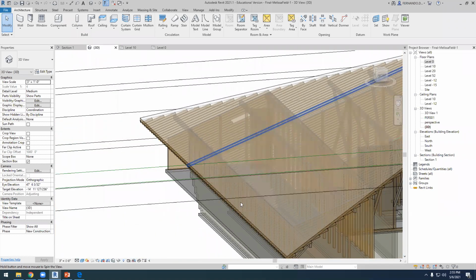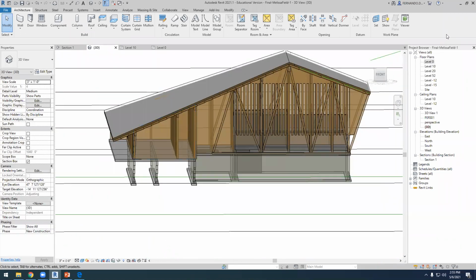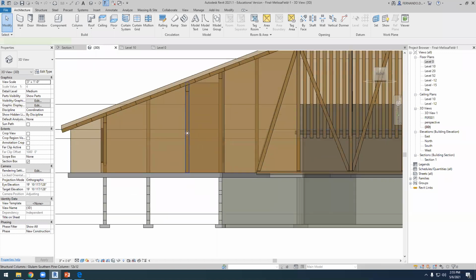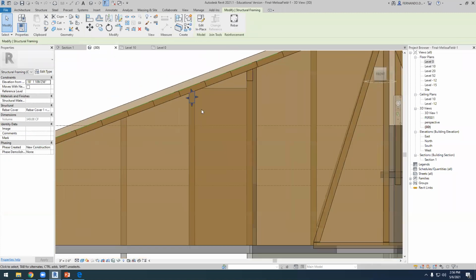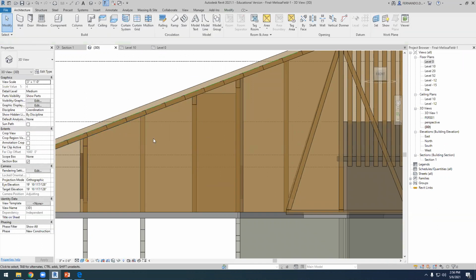So here we have structural elements, we have vertical and horizontal elements. We know that we have these two rows of this one and that one. And here we have the horizontal element, that beam here. And on that beam, the beam system is resting in this beam and that beam, okay? So if we open a skylight here in the middle of this roof, I would try to use this beam as one of the edges of the skylight, okay?